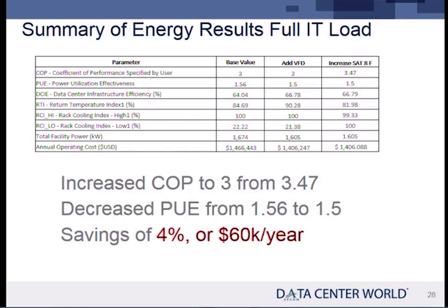On a thermal side, which is a better containment? Hot air. So the question is, what's better, hot aisle or cold aisle? And the answer always is, it depends. I prefer hot because you want to get hot back to that heat exchanger. That heat exchanger wants a very, very hot return. And if you do give it a hot return, the chiller is going to be better, the maintenance is going to be lower, you're going to have better MTBF.